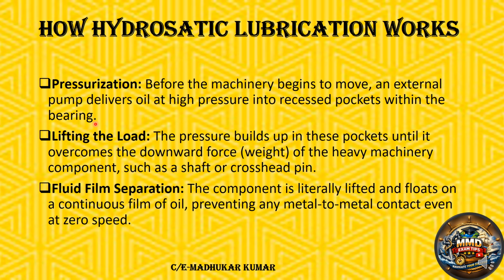Then, in the second phase, lifting the load. The load is being taken by the oil. The pressure builds up in these pockets until it overcomes the downward force, that is the weight of the heavy machinery components such as the shaft or the crosshead pin. So there will be a separation, and the oil is taking the whole load of the machinery.